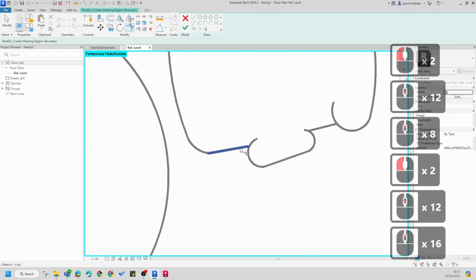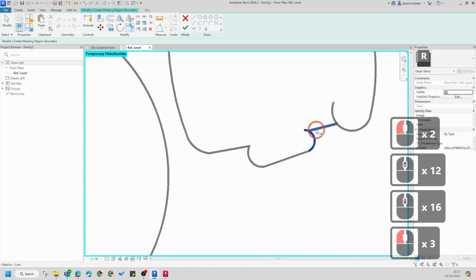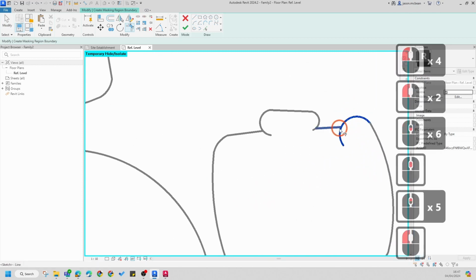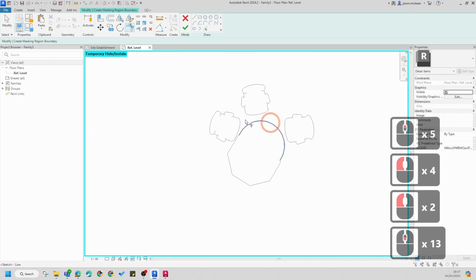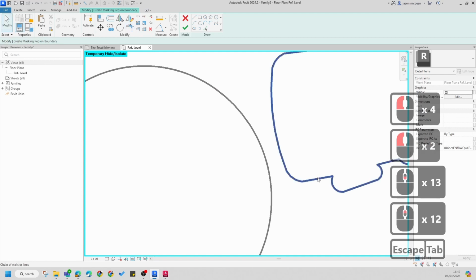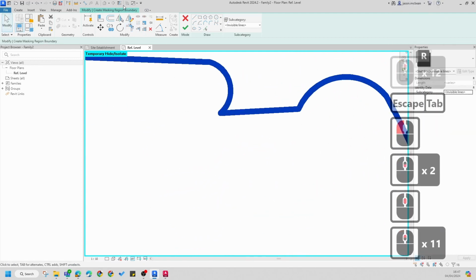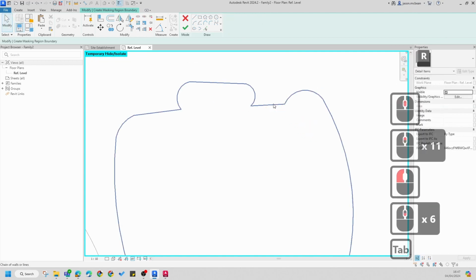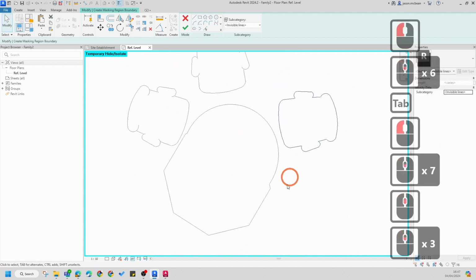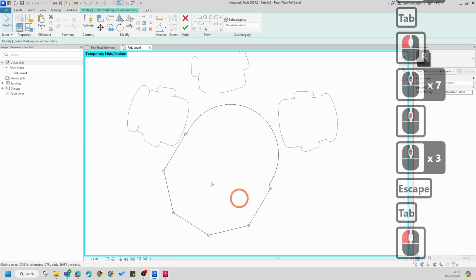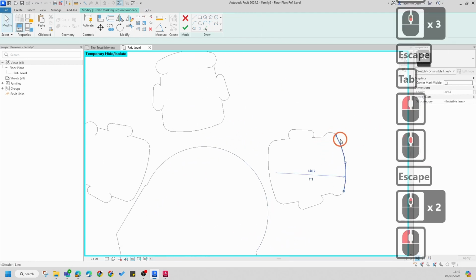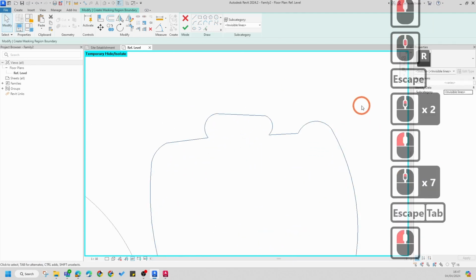Good. So here you just need to trim and make sure these are all closed loops, otherwise they don't work correctly. So this is very important, and you'll have a lot of bugs if this is not done correctly. So if I press tab now, it should be a series of closed loops. Switch off your line weight so you can see, so tab. There shouldn't be any open bits of line work, that's important. See, like that. So tab.